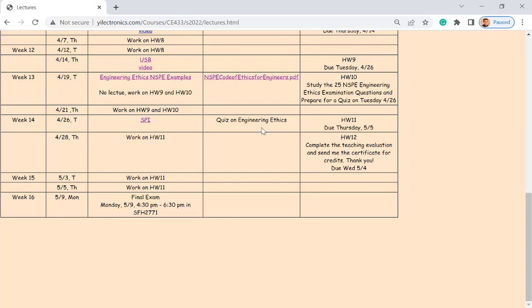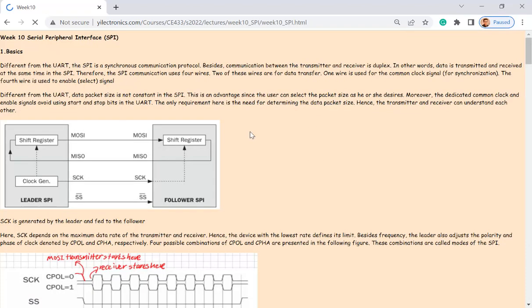Precision, yes. So this one can give you more values. It's being digitized. But the resistor is only changing the resistance that continues in the analog range. You have to form a voltage divider first, and you probe that voltage change using ADC. But this one already has ADC inside, so what you are getting is exactly a digital signal. So it's actually converting the light data into digital data in the form of a protocol which is called SPI. So we're going to take a look at it today.